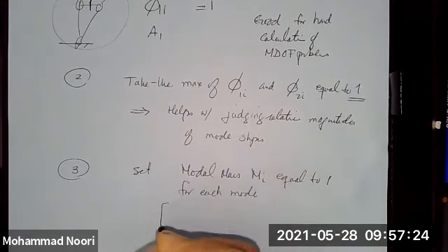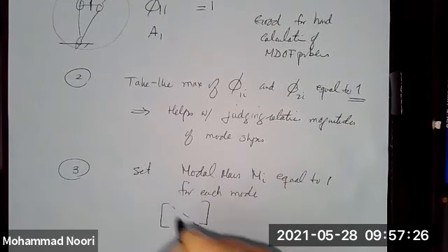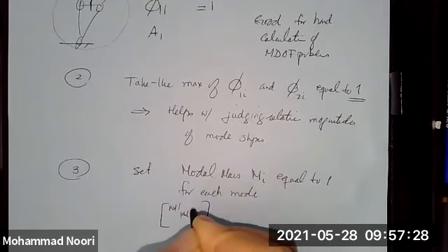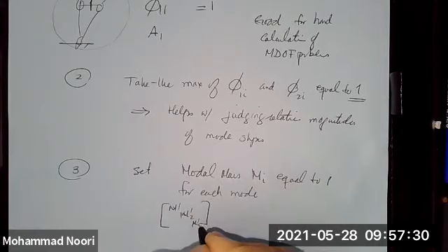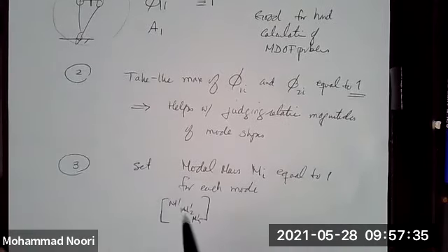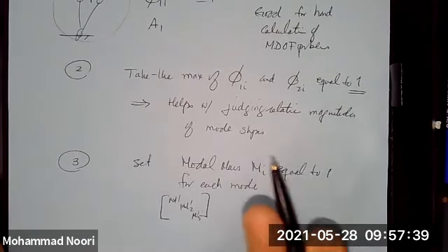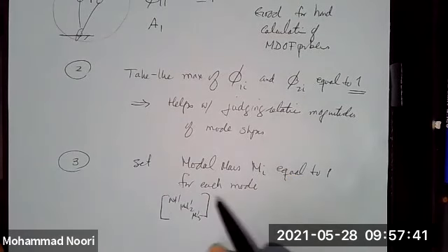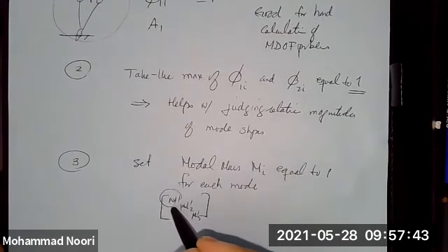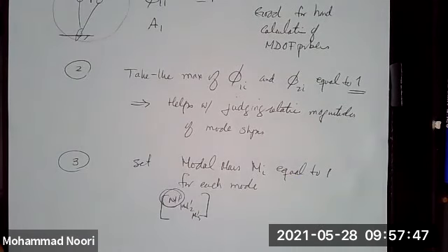I forgot to tell you that generalized mass matrix that resulted from the operation of orthogonality. So one approach, which is done actually in finite element, is that we set these equal to 1, okay? All right? And then find the relative value of these.